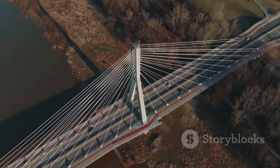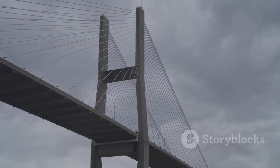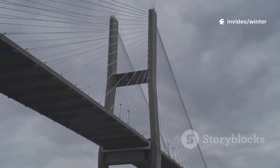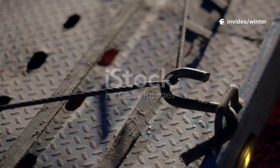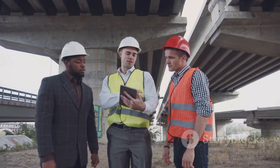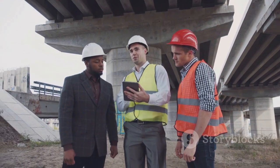Let's see stress and strain in action. Think of a suspension bridge. Steel cables hold up the roadway. When cars drive on, their weight creates stress in the cables. The cables stretch slightly. This is strain. Engineers calculate the maximum stress and use Young's modulus to ensure the cables only stretch within safe limits.